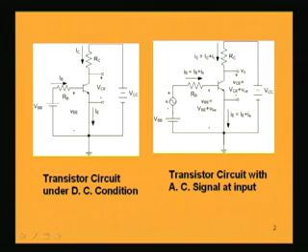If we consider the voltages, then the base to emitter voltage will be capital VBE plus small vbe, and the collector to emitter voltage is capital VCE plus small vce. Here we have the symbolic representation of the instantaneous current and voltage by small i capital C, small i capital B or small i capital E, denoting that this is the instantaneous current.